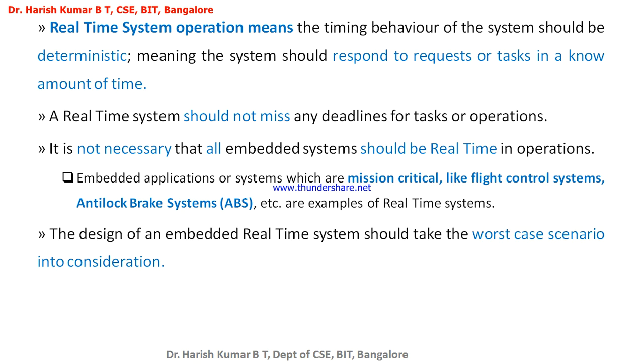Load the embedded systems heavily and observe whether it is capable of completing the designated task in a given time or not. If the system is not able to complete the given task in a designated time, then it is not a real-time system, and if you deploy this for use, then there may be a lot of problems. It may be a threat to human life, or a threat to the physical environment or the surroundings.